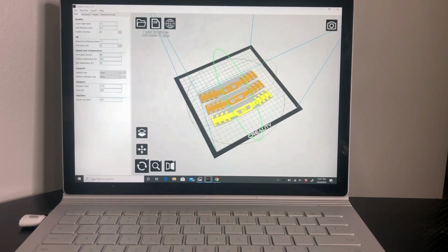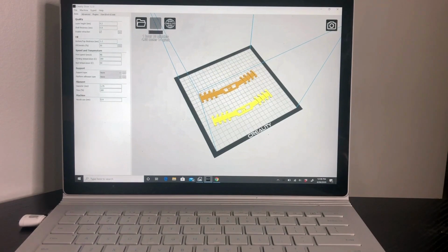For this particular one, print orientation is just the bottom completely down flat. For certain parts, for strength, print orientation is very key, but that's not quite a necessity for this particular part. Depending on where you're going to experience stresses, if you have any stress concentrations or anything like that with your part, each one's individually assessed at the time, and that'll be something you guys will learn from intuition. But I just wanted to cover that to bring it to you guys' attention.